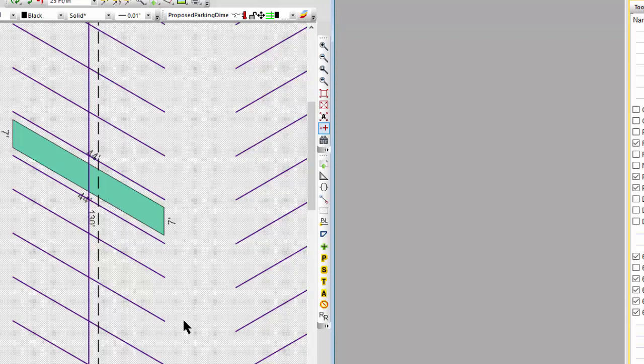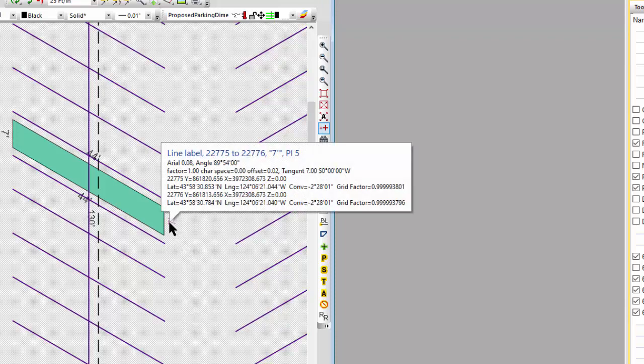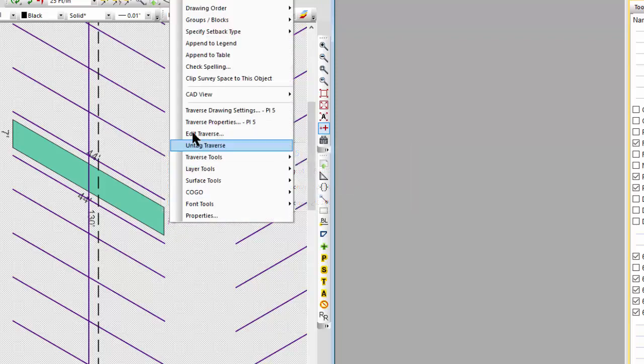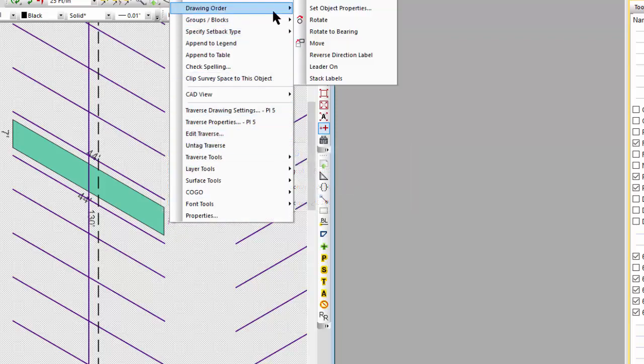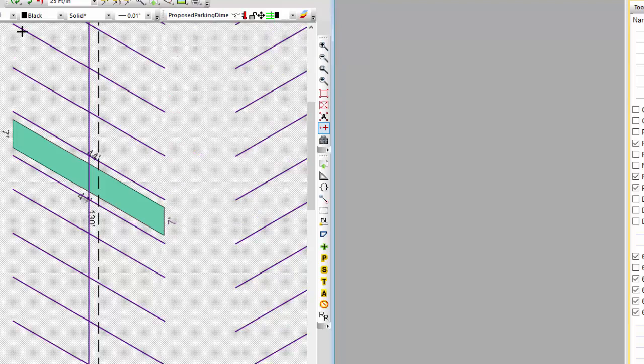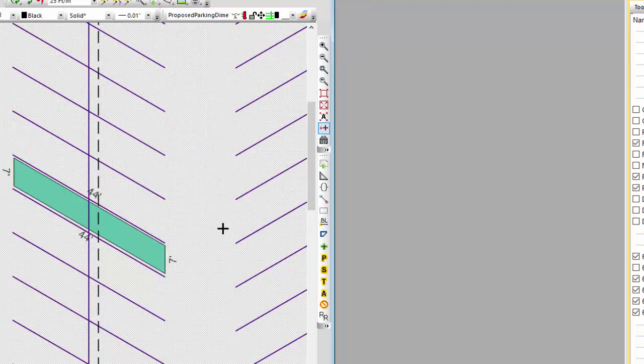I just did the same thing I would have done with a COGO Translate, but I did it graphically instead. And I do this all the time when I'm sitting there with a client and they want to stake the house out on the property, but they want to get just the right angle, the right view. We rotate, translate, do all that stuff directly just like this. So object, I can move it back, or I can just say undo and put it back where it was.